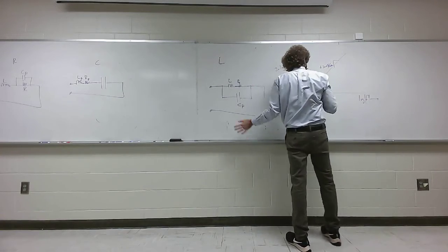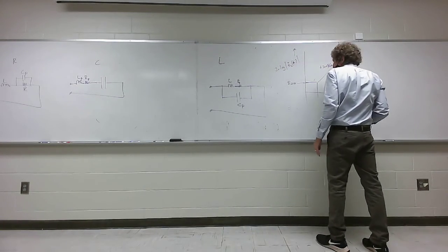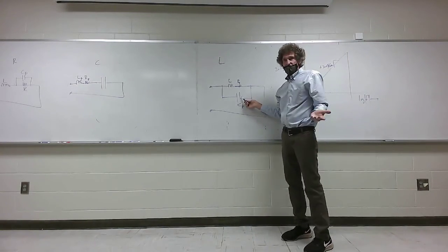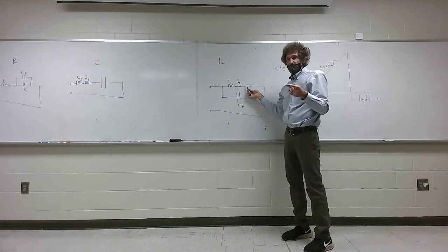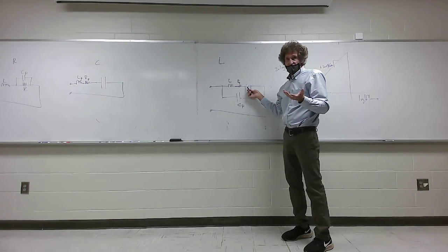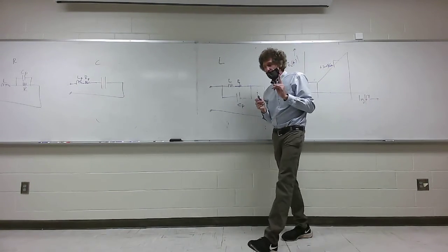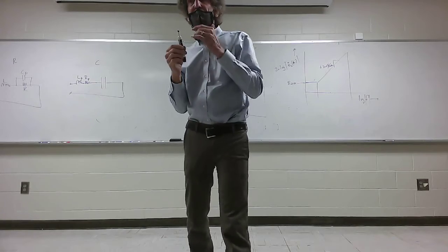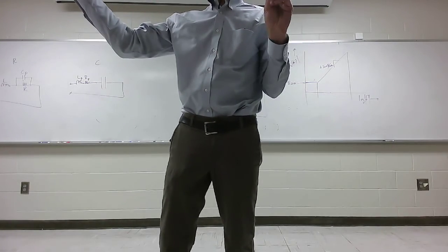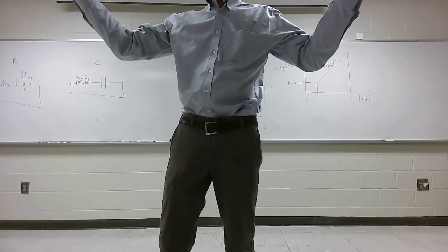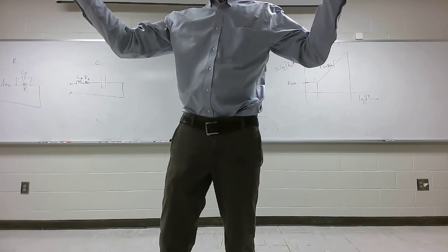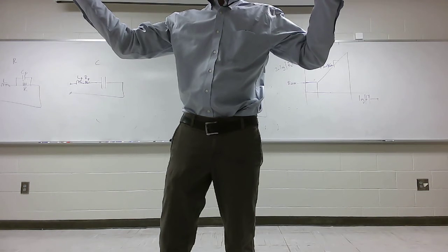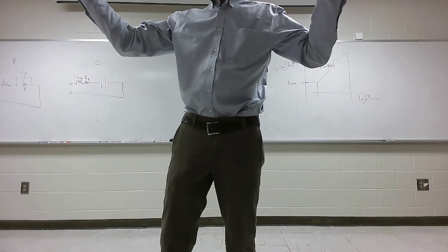Then it'll keep going up at 20 dB per decade until this capacitive reactance starts becoming equal to the inductive reactance. Do y'all remember when you have an inductor and capacitor in parallel, resonance happens when the inductive reactance equals the capacitive reactance? And the phase of the currents are exactly, one is 90 degrees ahead, the other is 90 degrees behind the voltage. The net effect is no current passes when you're at resonance.